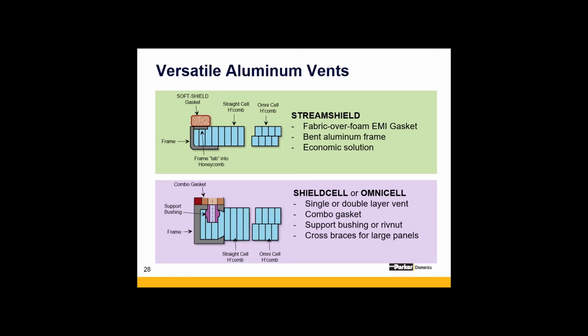With a plating that can add a higher cost, you're going to see a shielding effectiveness increase. It can also improve the shielding of these vents, considering they kind of straddle the line between the higher end of the low performance and the lower end of high performance. Finally, vents are actually going to include cross braces if they get larger than 12 by 24 inches, for example.